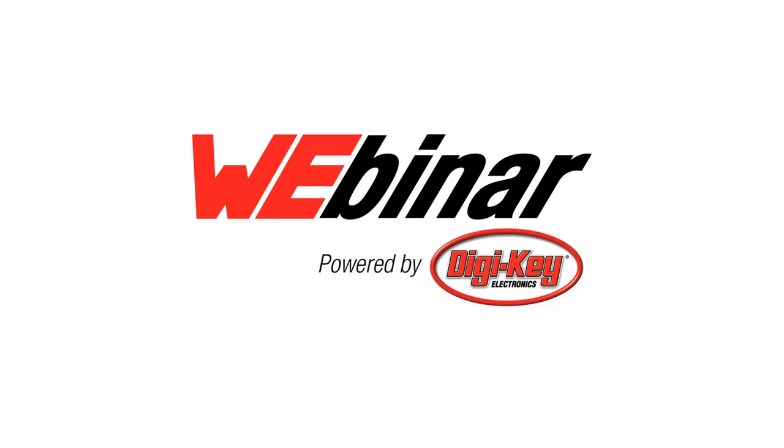Okay, so I'm guessing you're asking about whether you should put a conformal coating, a lacquer, over the top of the crystal, yeah? Mixed opinions about that one. Some people do, and it's absolutely fine. I do know some really large scale manufacturers and big household name electronics guys that deliberately block the crystal from the conformal coating.